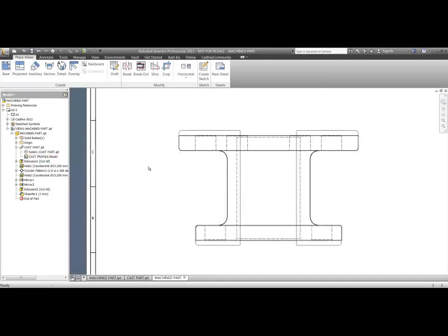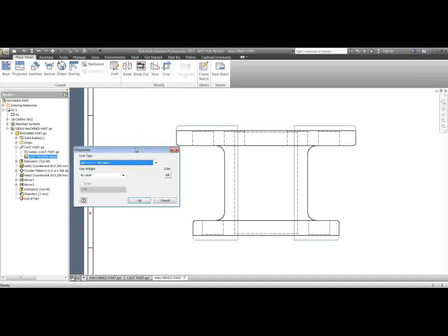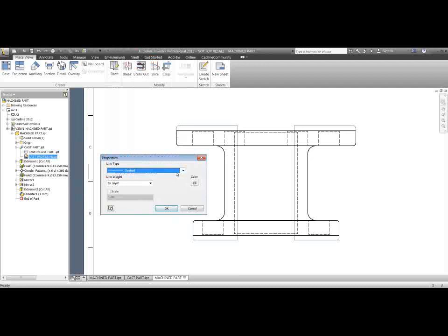Once we've done that, that's looking much better. We can see that sketch now. It's not quite the display that we want it to be, so I'm going to right click on it and select as edges. This is third from bottom in the list. If you can't see this in the drawing, right click on that sketch and hit select as edges. Once I've done that, I can then right click and pick properties, third from top, and now I can choose my display.